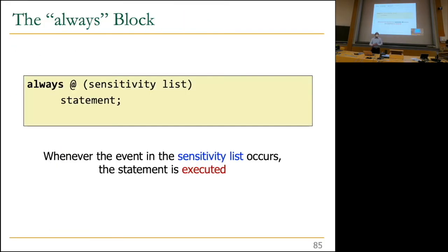Okay, so this is the always block, basically. It's interesting because we're going to introduce it to implement sequential logic, but you can implement any logic in it. You can actually implement combinational logic as well. But the main purpose of introduction is really for sequential logic. It can ease some of the combinational logic implementations as well, or descriptions, I should say descriptions. We're going to describe combinational logic as well using always block. And you will see why, because some combinational logic is not easy, for example, to describe, or it becomes very cumbersome to describe without an always block like this.